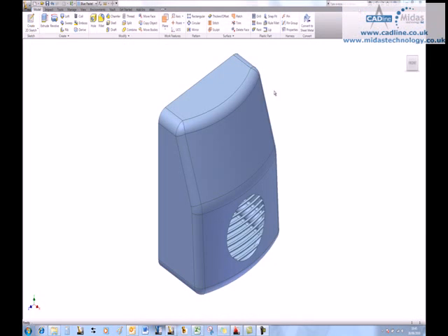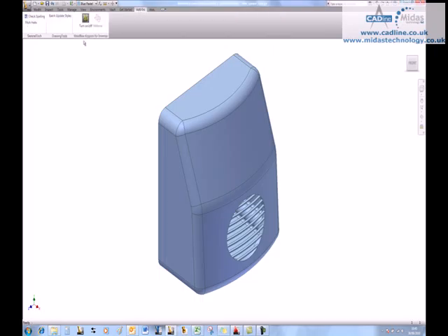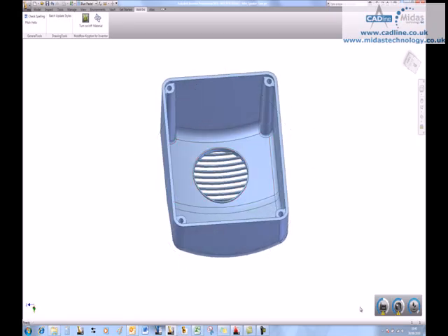But what happens is once you've downloaded this, inside of Inventor, in your add-ins, you will now see Krypton, Moldflow Krypton from Inventor. The idea is that you can then turn this on, and what it does is it loads up three little icons down the bottom of your screen over here. Project Krypton is designed specifically for plastic component design, so you can turn it on and off depending on the components that you're designing. Obviously in this instance we're designing a plastic part, so we want Project Krypton to be turned on. What it's going to do is have a look at a few things of the three down there.